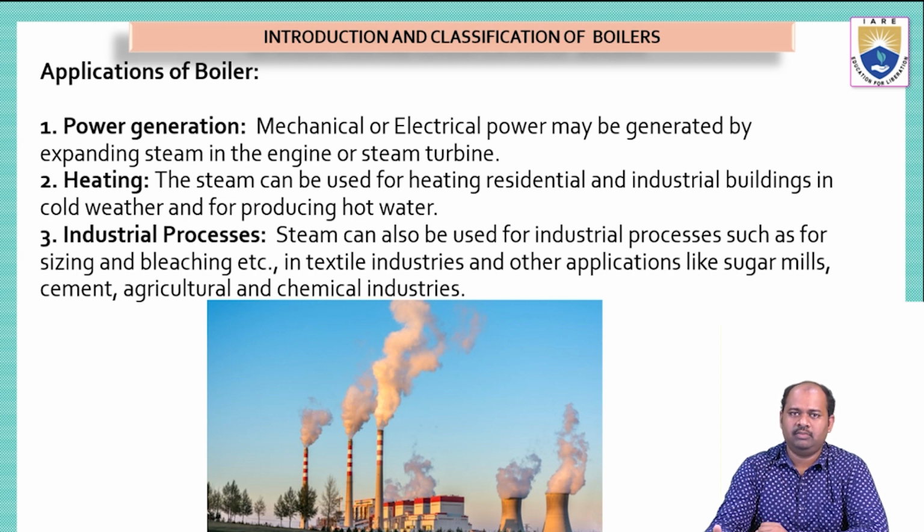We know there are some thermal power plants in India and all around the world. These thermal power plants were able to generate electricity with the help of the steam only. The two main raw products required for power generation in thermal power plants are coal and water. Now, what happens is we take the water in a closed container, that is the boiler. We supply heat that is generated from the combustion of coal, and this heat is taken by the water and it is boiled up to its boiling point, where it will be converted into steam.